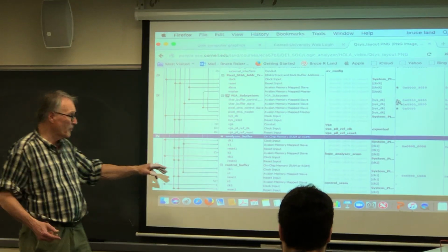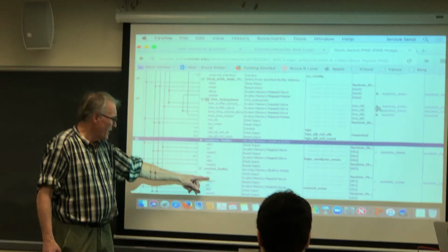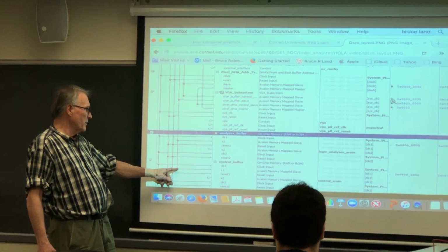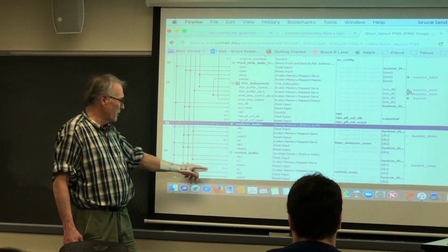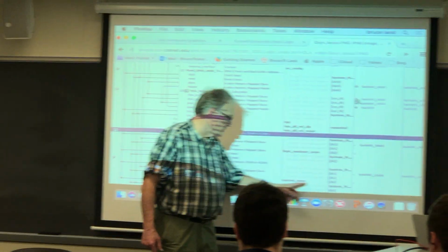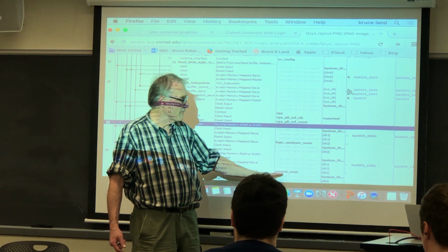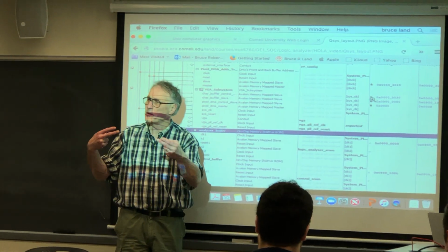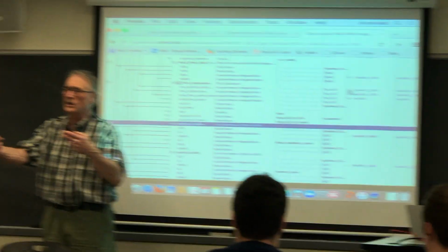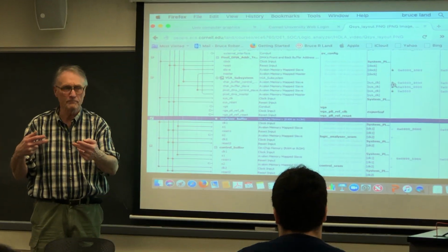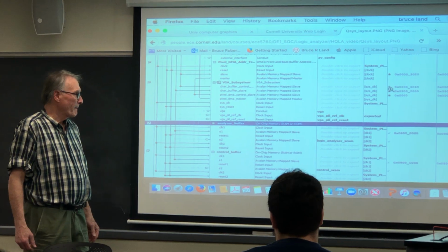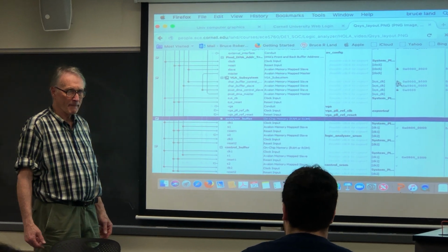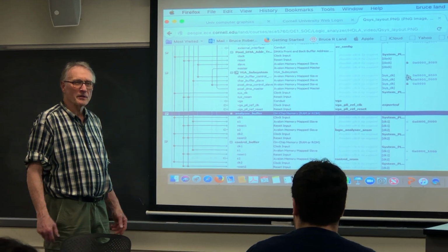Likewise, the control buffer, which is another block of RAM, has one port on the Qsys bus going back to the ARM, and the other port is exported into the FPGA fabric so that the HPS and the FPGA can handshake through memory. I like that particular structure a lot.